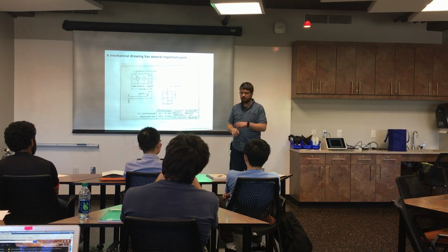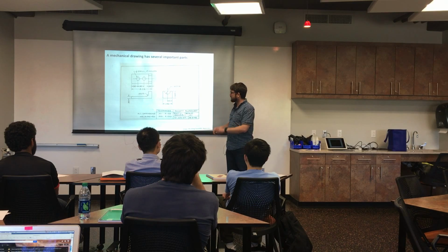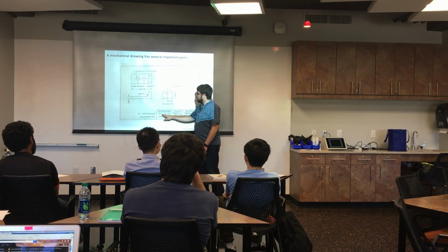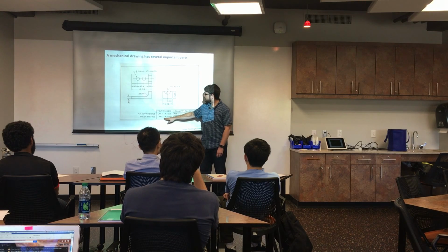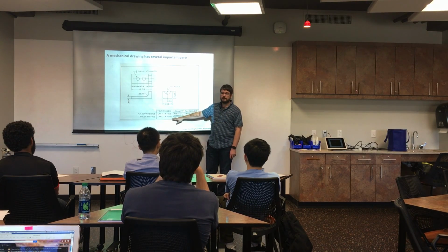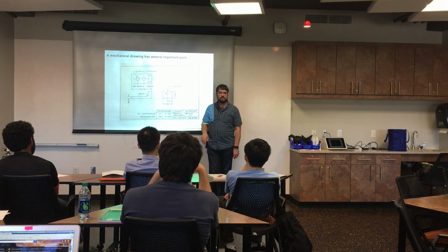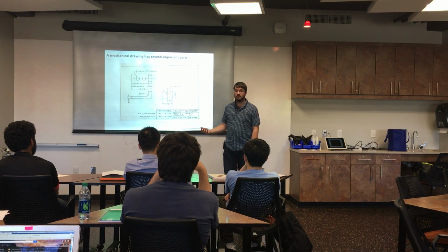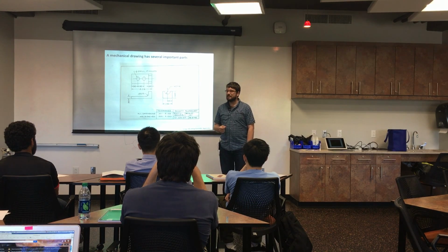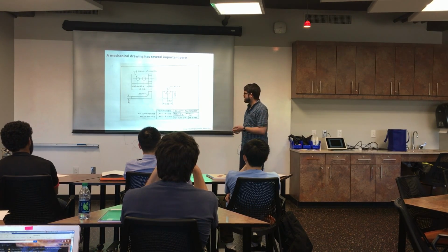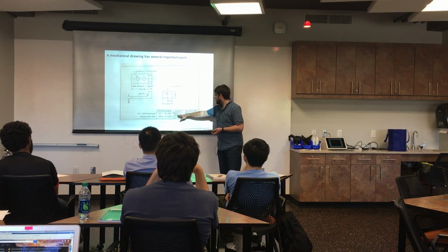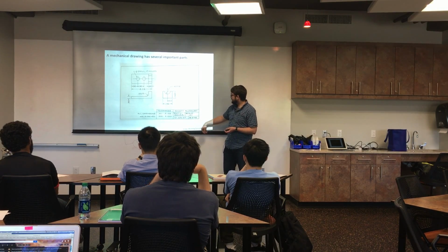Specifying tolerance, again, we'll talk about it at the end, but it's a really important thing to do here. If you've got two places after the decimal, the tolerance is plus or minus 20 thou. 3, the tolerance is plus or minus 1 thou. Otherwise, the machinist would probably assume, and I know our shop assumes, that you need their highest tolerance if you don't specify a tolerance. And the highest tolerance is expensive. So you want to specify low tolerance where you can deal with it. And so it says the material here is brass, it's got a date.